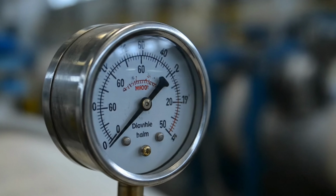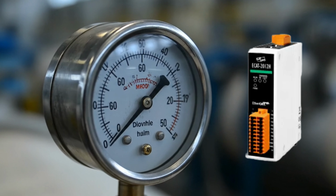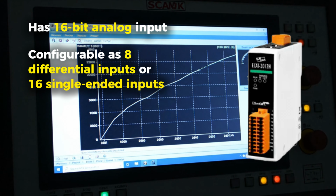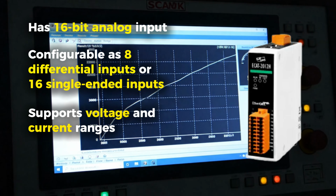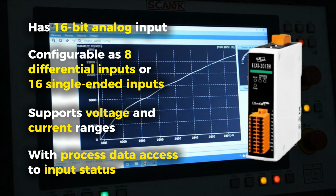Now, EtherCAT is also used in applications where analog data needs to be acquired and delivered efficiently. For analog input, you could use the ECAT 2012H. This module has a 16-bit analog input. It's configurable as 8 differential inputs or 16 single-ended inputs. It supports voltage and current ranges, and it has process data access to input status.